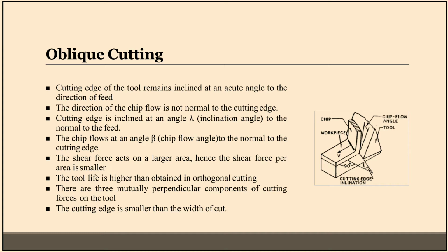The shear force acts on a larger area, hence the shear force per area is smaller. The tool life is higher than obtained in orthogonal cutting. There are three mutually perpendicular components of cutting forces on the tool. The cutting edge is smaller than the width of cut. There is a picture of oblique cutting, and mention here chip, workpiece, cutting edge inclination, chip flow angle and tool.